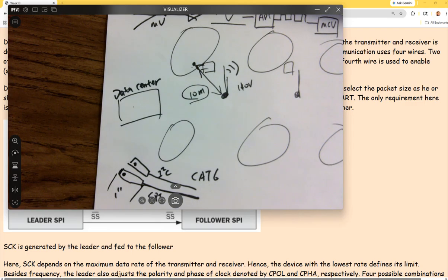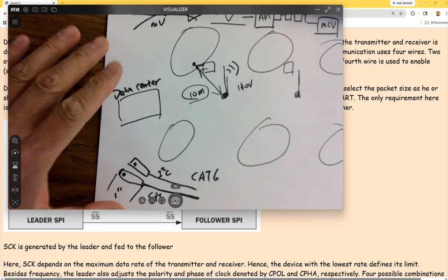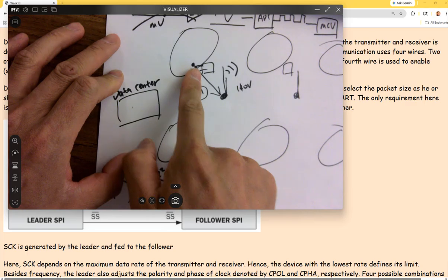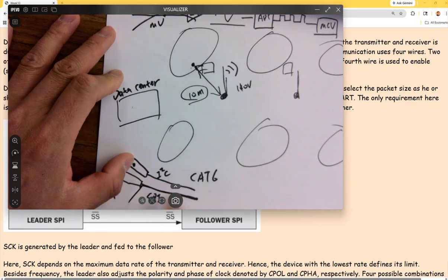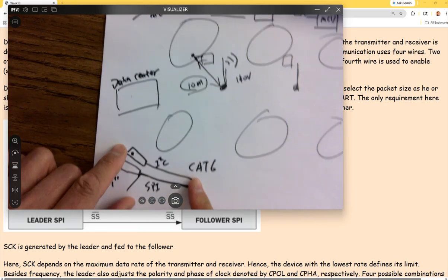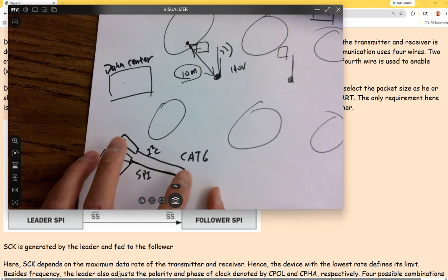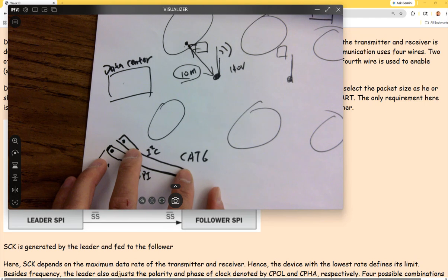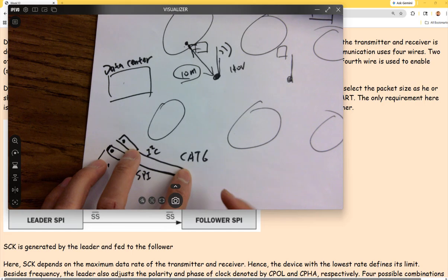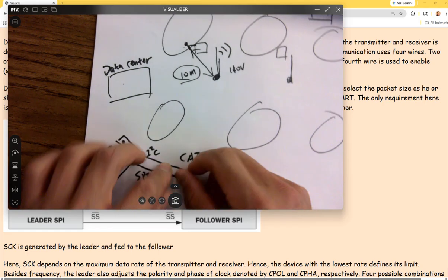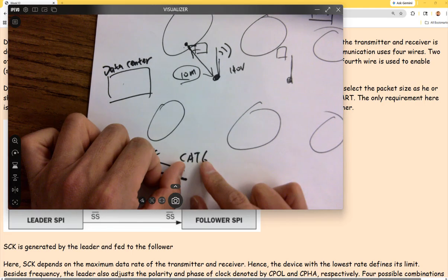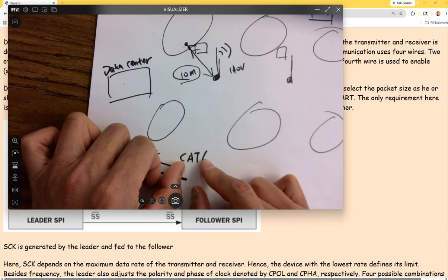And I actually tested. I put an I2C sensor over here and probed the temperature data. Because this cable from the manufacturer is not very long, they don't know you are using it for that long distance, right? So this is probably only a foot or something. And then right after the cable, you strip it, and then you connect it to a Cat6 Ethernet cable. And for some reason, that cable is designed for long distance. It's probably lower parasitic capacitance.